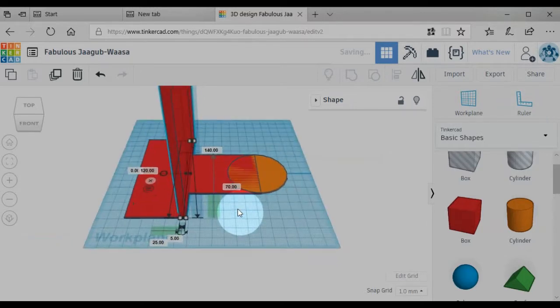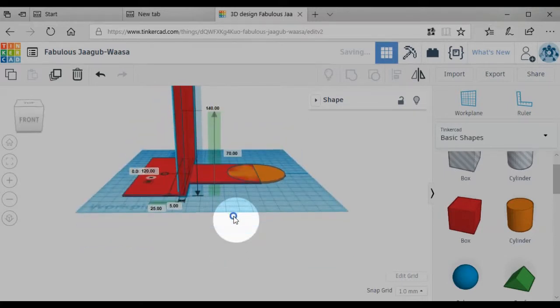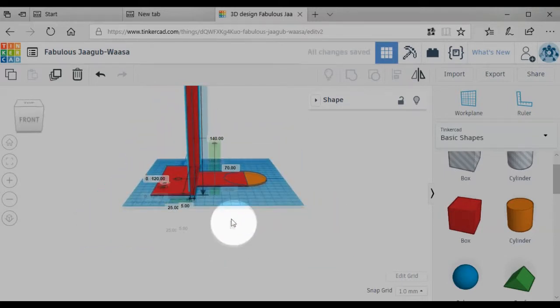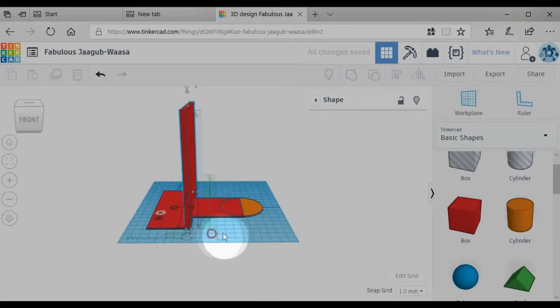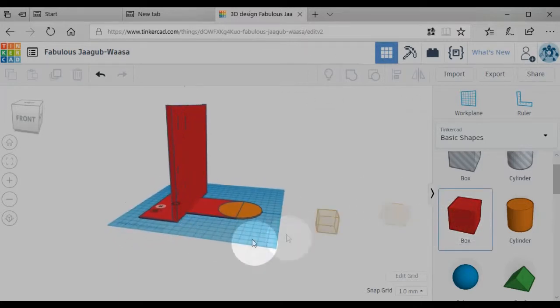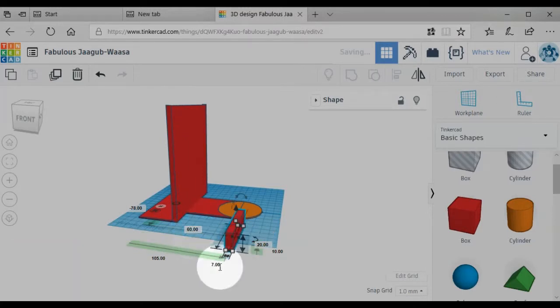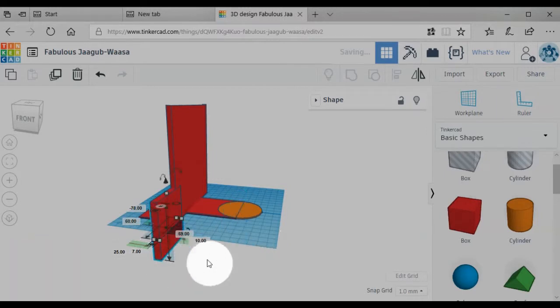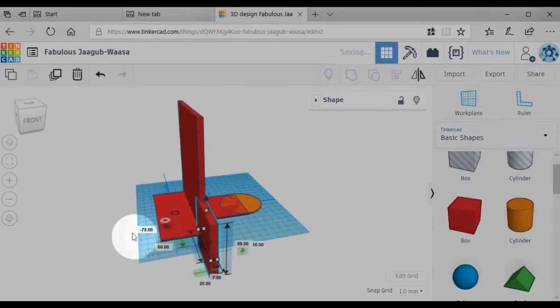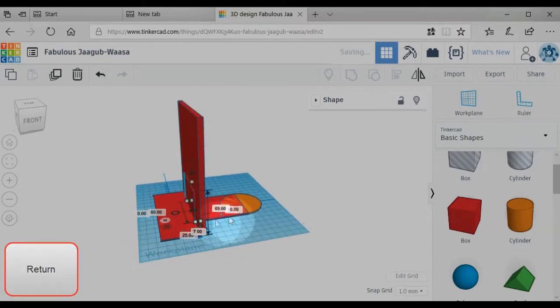This bookend is functional, but has room for improvement. Adding a hole to the brace will make the bookend stackable for better storage. This begins by making a cube and sizing the x-axis to 7 millimeters across, sizing the y-axis to 60 millimeters deep, and sizing the z-axis to 69 millimeters tall. It is then positioned on the x-axis 25 millimeters to the right, on the y-axis at the center, and on the z-axis 35 millimeters high.